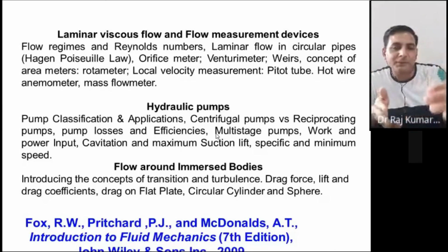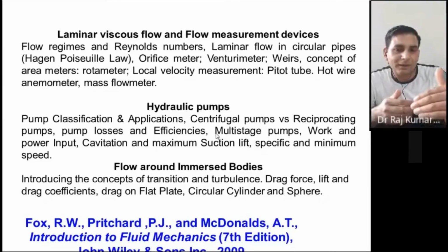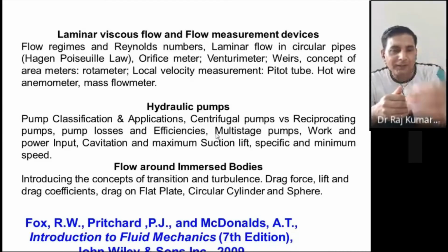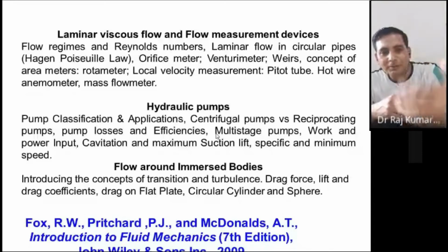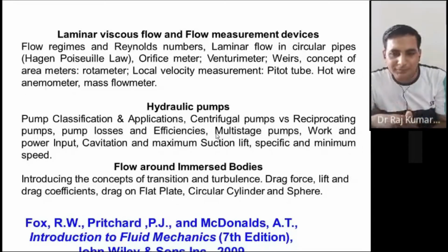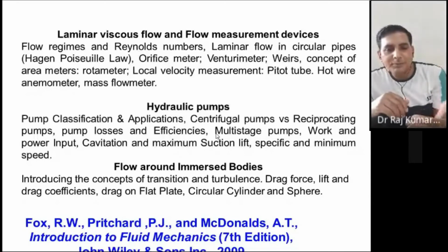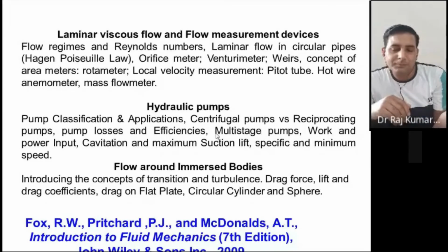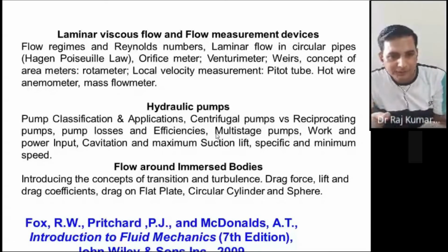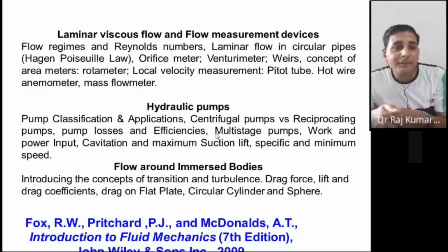So you have a pump which will work to a particular height or distance. After that, you need another pump, another pump. That's called the multi-stage pumps actually. Then you need power. So how much power would you want to give? Each pump would have a power in terms of your volumetric flow rate. The more the flow rate, the more the power consumed. Fine. So then you have cavitation.